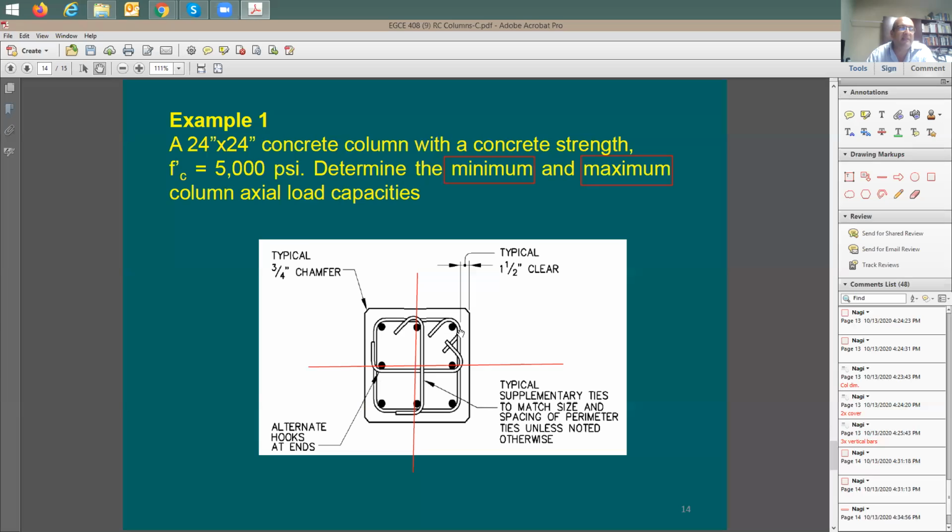So you should be able here to divide safely. You divide here by 4 with no fraction. So 16 is okay, 24 is okay. I'm just talking here about without thinking about the column size yet. So how about 24? 24 is good. 36 is good. How about 30? Is 30 going to be okay? Can you put here 30 rebars in this column? Yes or no? No. See, no, you cannot. Maybe 32, maybe 36, you should be able to.